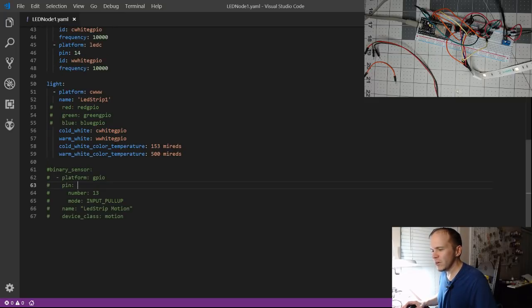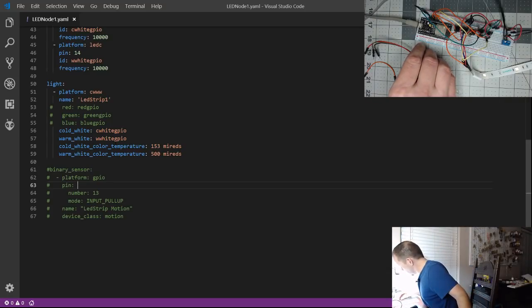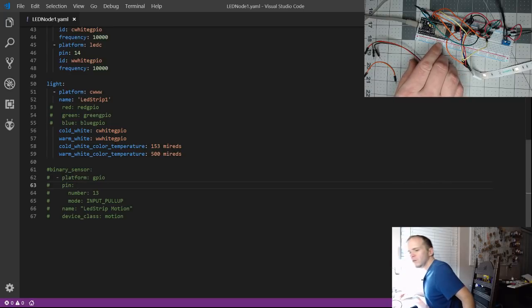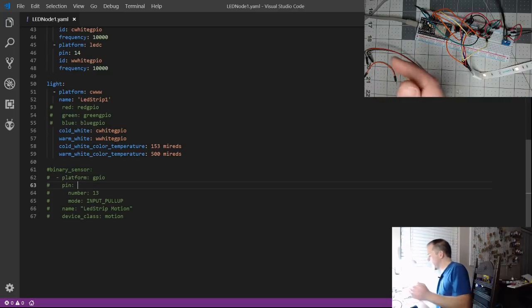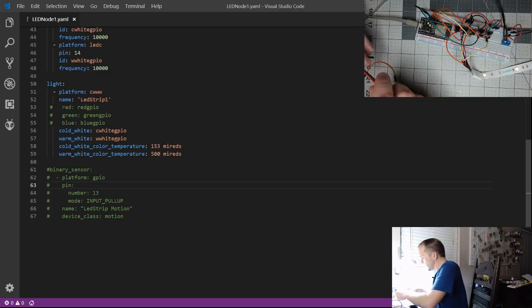Try hooking up to D4, see if you get the... I don't know if I have D4. Oh, are you using an ESP8266? I was thinking G4. I don't think they do a breakout on that. That must be used by the flash or something else. Yeah, no, there is G4. I do see GPIO4, but I can't get to it because it's on the side. I scooted the board all the way over. I'm going to use 13 again.